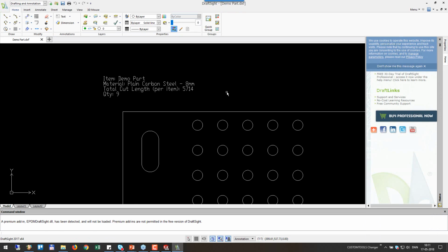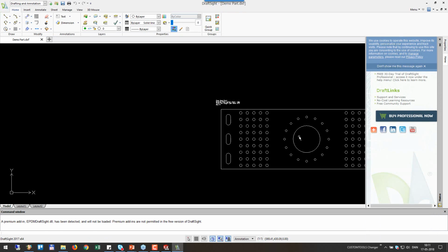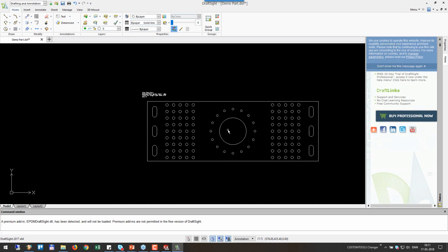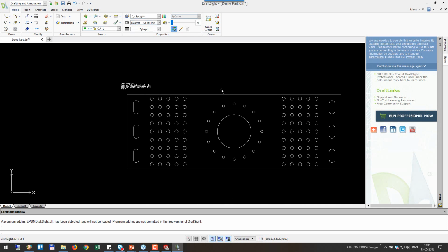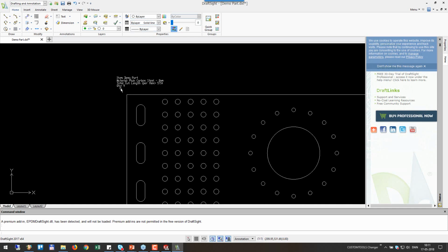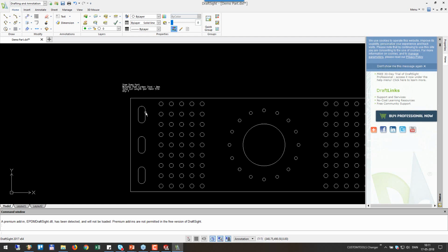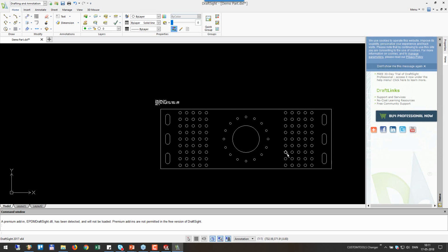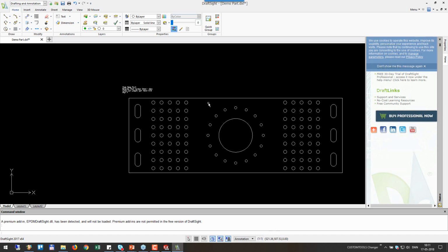Yeah. So these are some of the tools that we offer as well for everyone using sheet metal. Just another info for the node. We can add almost any information you want in this node. If you wanted to have the number of pierce points required to do this part, in this case that would make sense because that would have an impact on your manufacturing process.